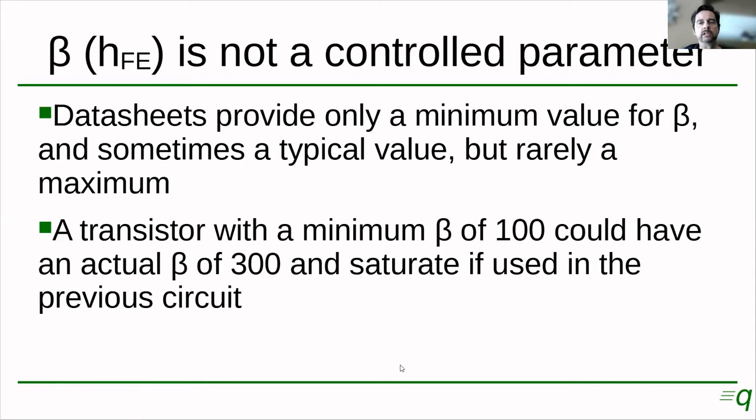you cannot really know in the previous circuit whether that transistor will be saturating or not. So you cannot know whether that transistor is going to be acting as a current source or saturating at 0.2 volts collector voltage, okay?